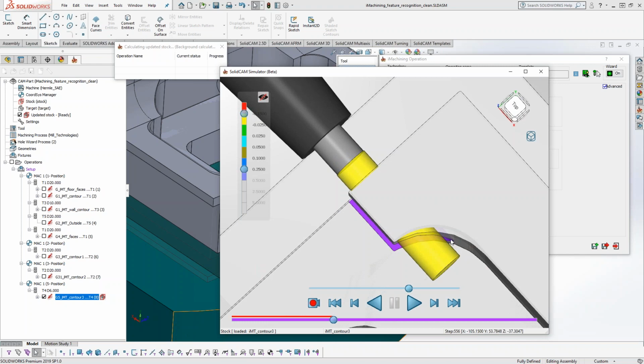What's kind of cool about this is, when we think about cutting at the CNC, we talked about the ACPs before. The ACPs have to deal with how much of the tool is engaged in the material. When we look at this cut here, when it first starts to cut, it's only engaging this much of the tool, and then as it goes to the very bottom, it's engaging more. Cutting with iMachining long enough, and I think our customers know this, when this cuts in the CNC, I might hear a different pitch and tone at the beginning of the cut compared to the end.